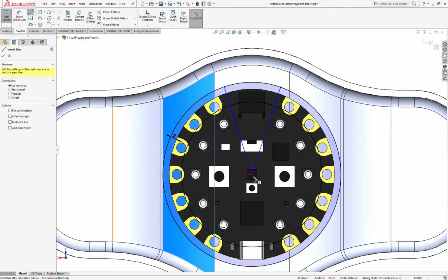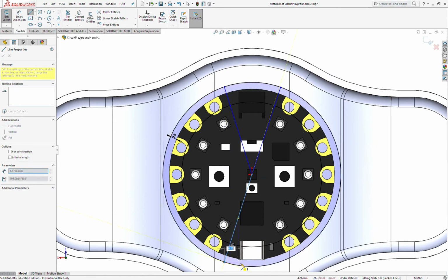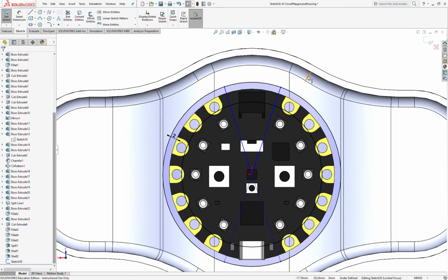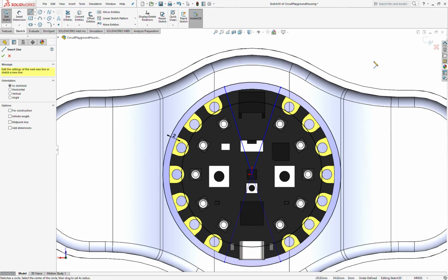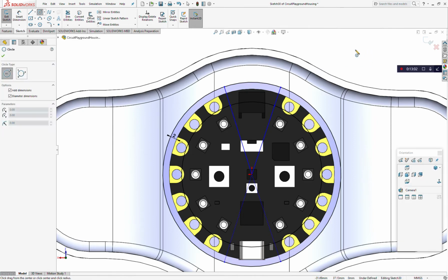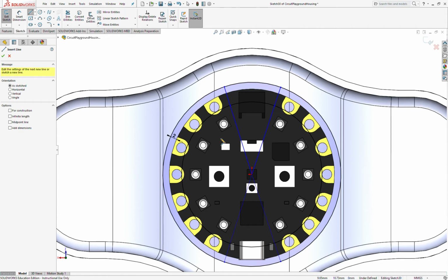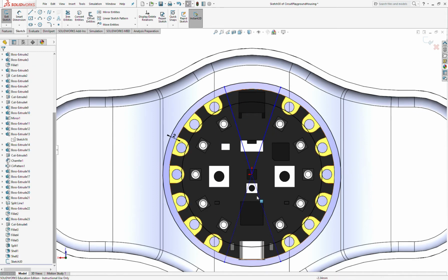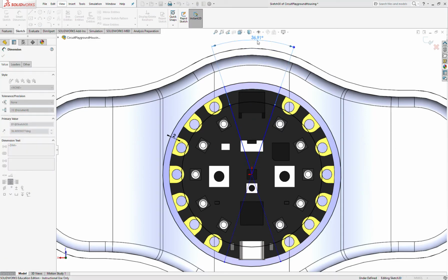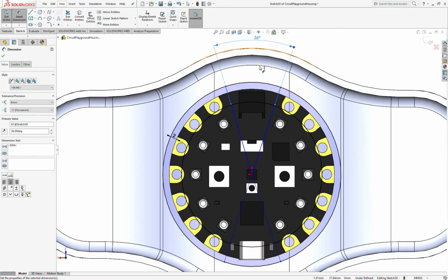Same here. I don't know if this is going to show up on the video, but if you hold right click and drag, you get this quick selection menu. Right and drag to the left is a line, up is dimension, right is circle, and down is square. I tend to use this a lot. It's really fast for these quick actions. So sorry if that gets confusing or if you're not seeing that. But that's generally how I'm making these lines.